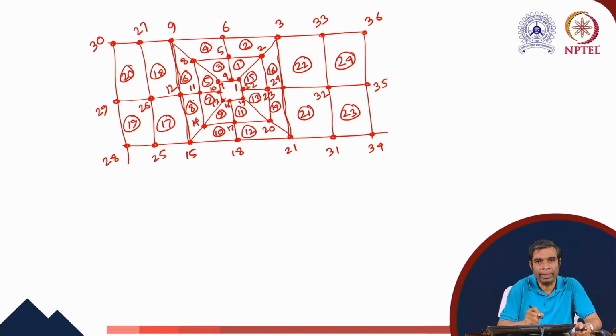So we have to assign the correspondence that the third local node of element 17 represents the fourth local node of element 8. This correspondence should be defined for all the nodes which are located at the interface. Once it is done, we can generate the final mesh plot.